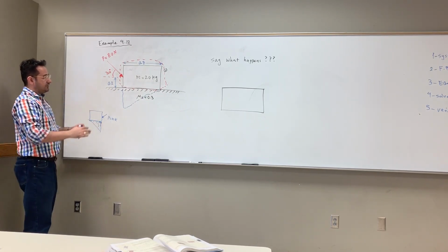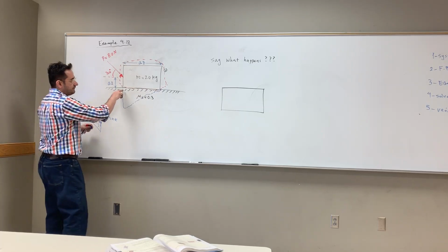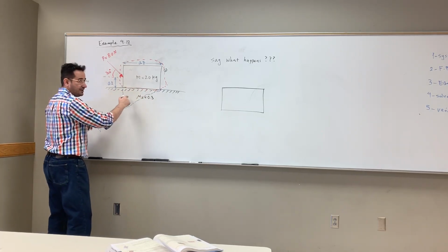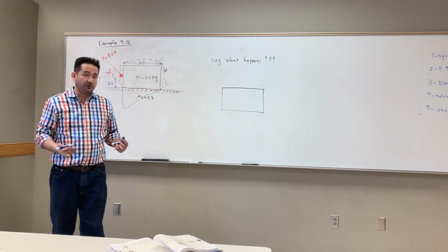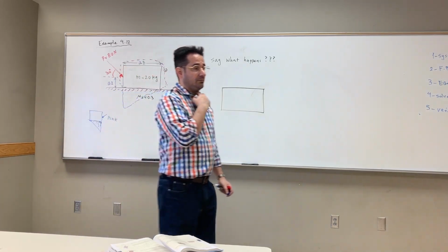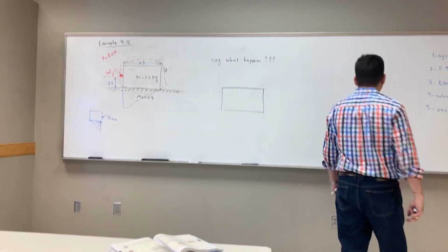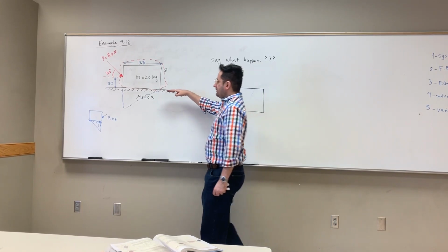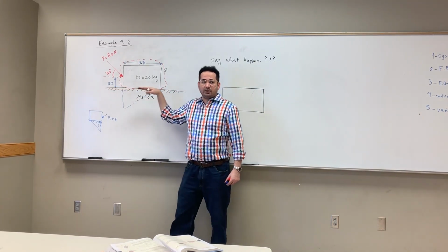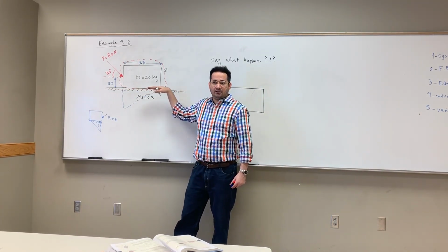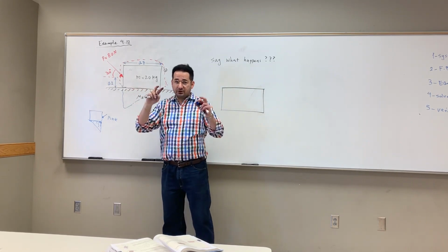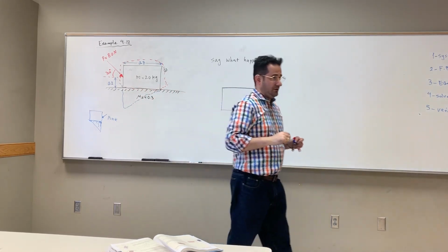So this friction force has a geometric center that we don't know because it is such a complicated force. But we know that the total reaction is a friction force this way. Why this way? Because that's the opposite direction of possible movement, right?